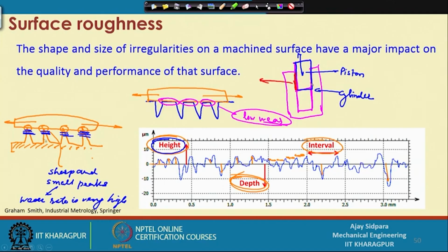If this interface surface is something like this, then the wear rate will be very, very high, and after some time you will have some type of opening between these two. It will not be a completely smooth fit. So, your cylindrical surface, that means your piston, and then your cylinder will be something like this, a very, very large magnified view in this case. So, after this wear, what is going to happen? This is going to happen in this case.